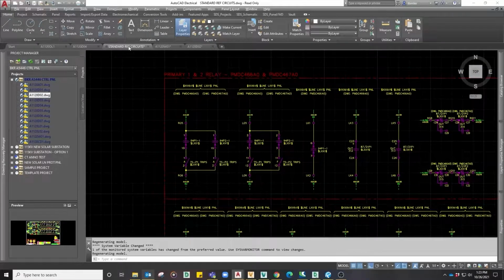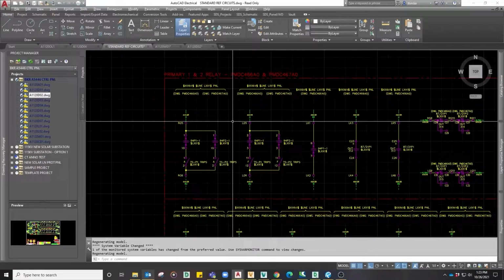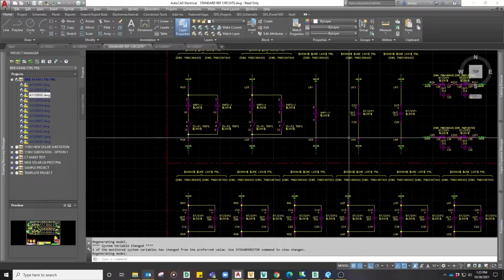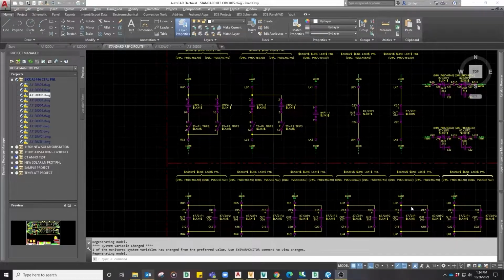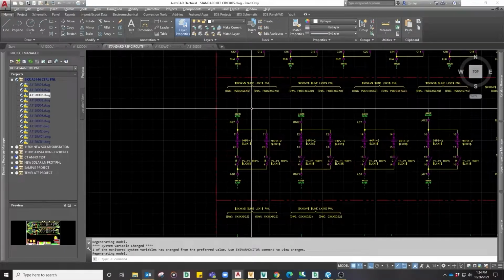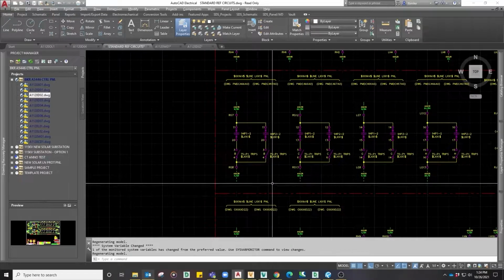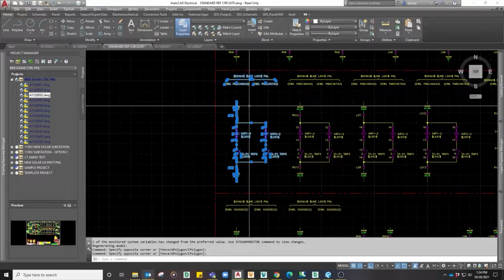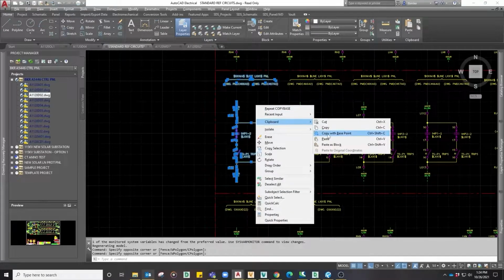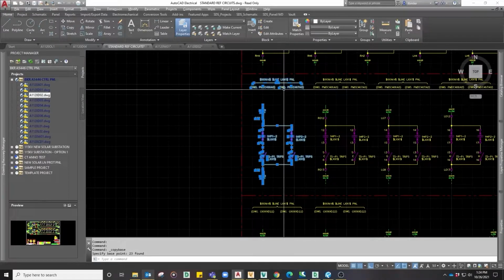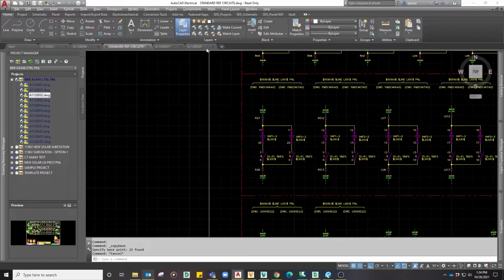It's always important to check the connections to make sure that they're actually snapped to the connection points. This is the core design procedure in a nutshell. At this point, it's a matter of going between the reference circuit drawing and the circuits in the panel drawings and doing a Control-C, Control-V to copy all of these circuits into their main breaker circuits.